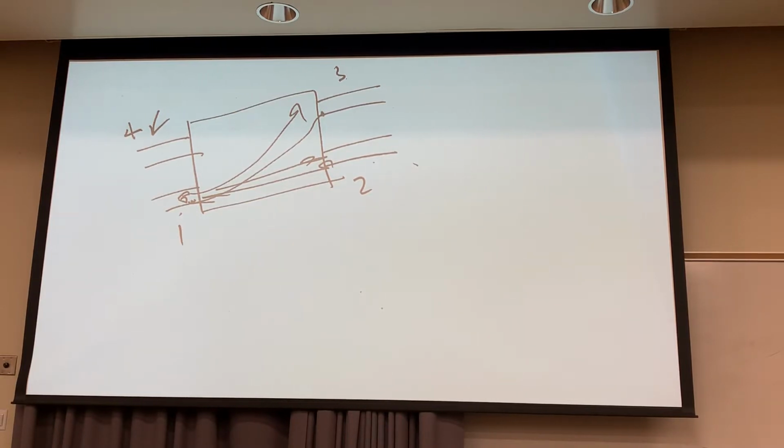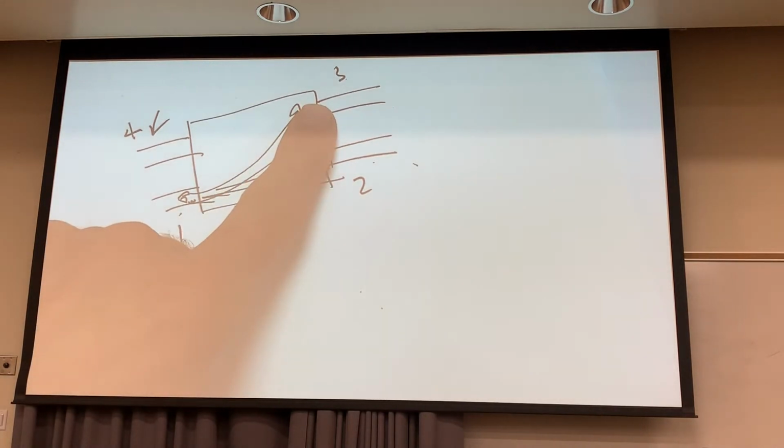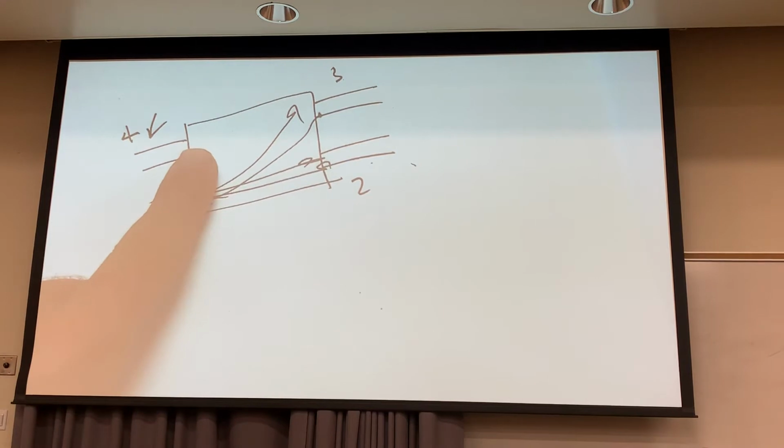You have enough of that signal there for synchronization work, things like that. And then there's a dead port there. If you look there, he calls it the isolation port, doesn't he? Isolation means you don't want anything there. But I could foresee a point where maybe they want 30 dB of shunt to here of loss, and maybe 60 dB here for some other reason. I can't think of one right now, but I know that there are some weird things.